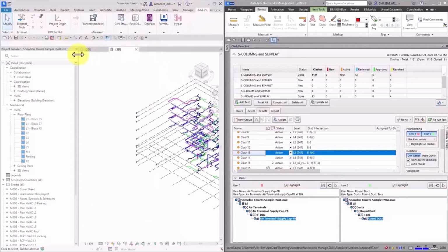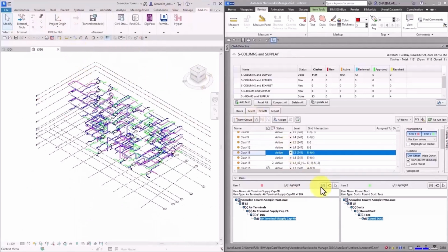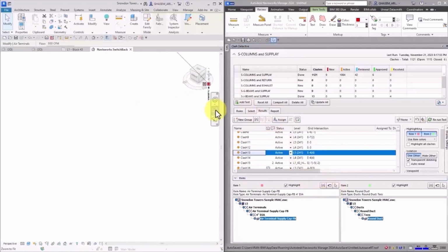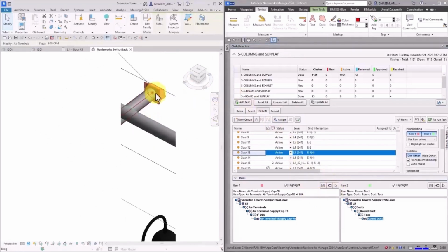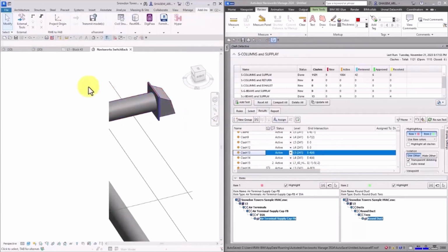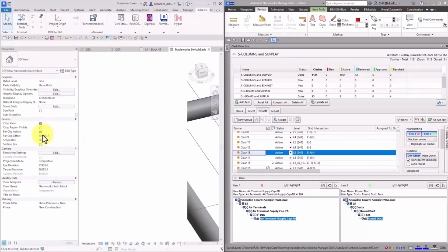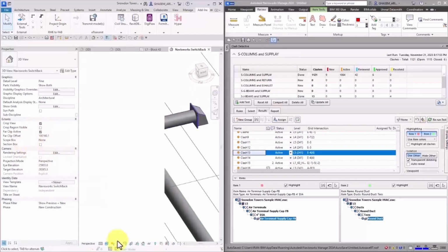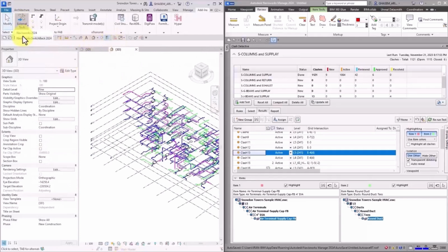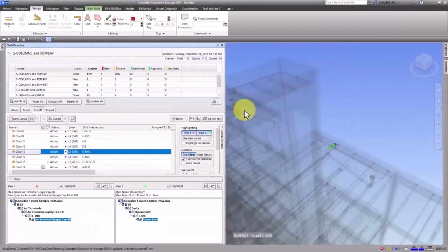This one is switchback. Here in Revit, I activate switchback. Now when I click on this, it will return my model to Revit with the exact location of it. It says it's here. Now you can solve the clash. You can remove the section box. Okay, like this, in the 3D view. Now export it again, apply this to the previous file and refresh it to have updates.